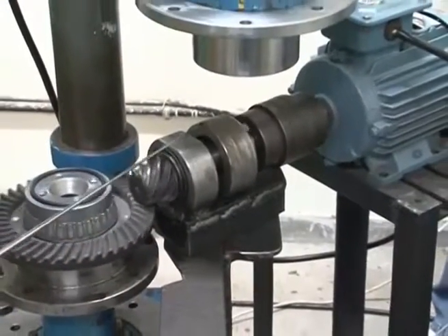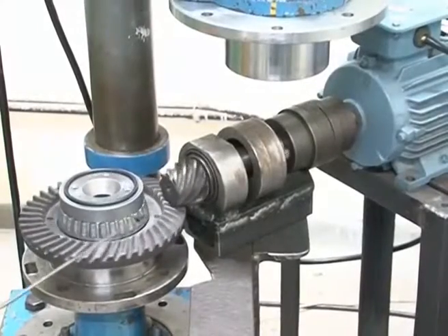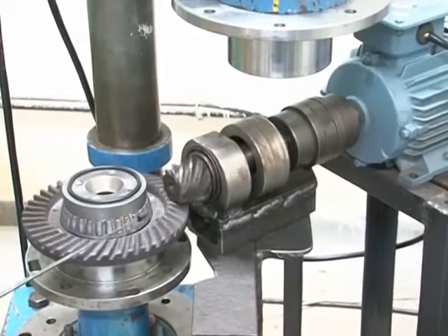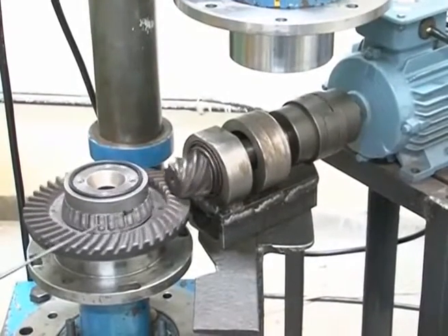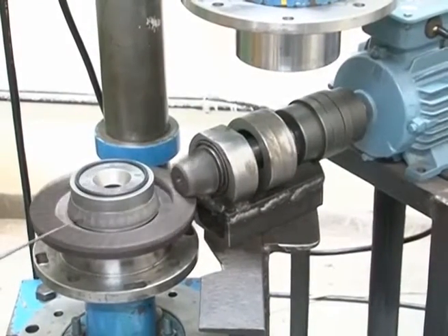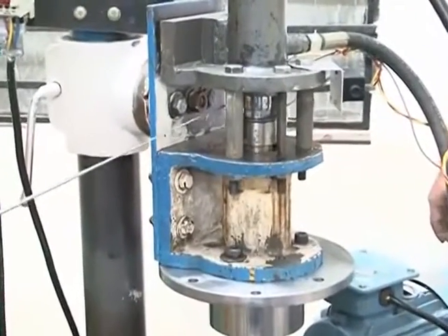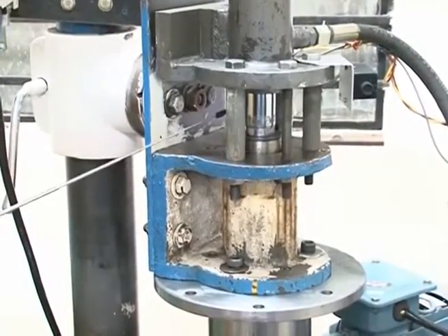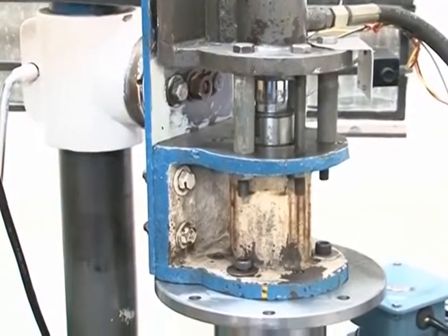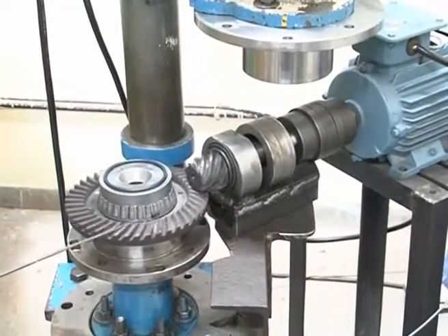Motor in turn rotates the pinion. This pinion rotates the crown and crown internally rotates the workpiece. In this way we are giving the external rotational motion to the workpiece. Now you can also see the reciprocation motion of the hydraulic piston. This piston pushes the medium and this rotational motion gives the rotational motion to the workpiece.